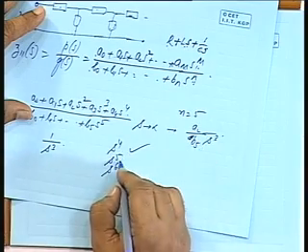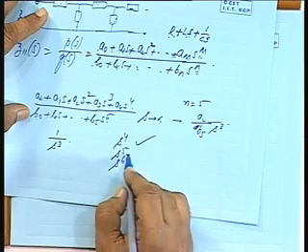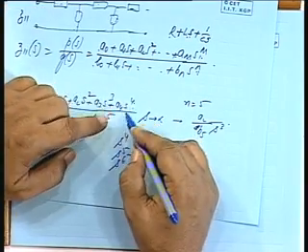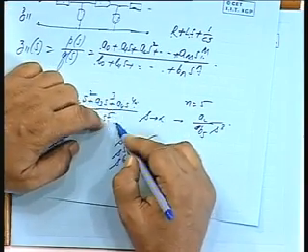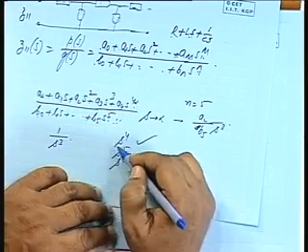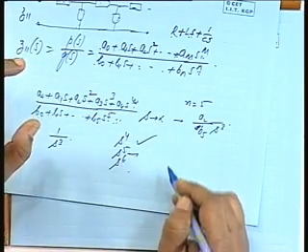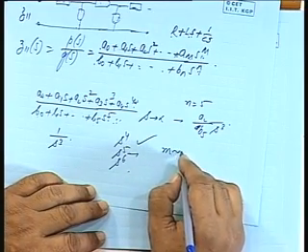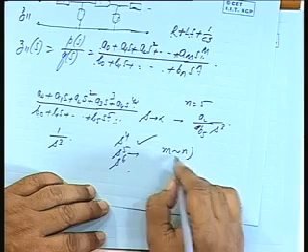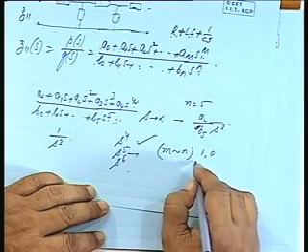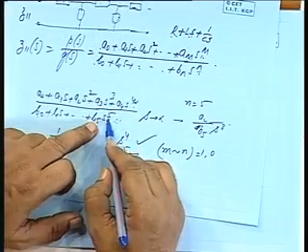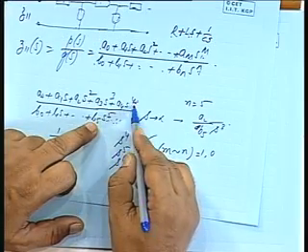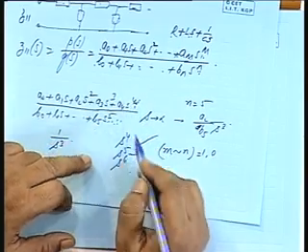That means if I have the maximum power of this as S to the power 5, the other can be either 4 or 6. That means the difference in the maximum power of the polynomials, m minus n or n minus m, can be at the most 1. So if this is S to the power 5, it can be 1 less, 1 more, or equal. The difference cannot be more than that. Is that all right?